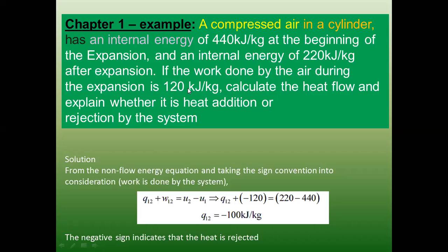Work, because here, the work done by the air means this work is done by the compressed air. So compressed air does work, which means the energy level of the air is reduced. It does work on the surroundings, not received but delivered work. So as a receiving of work, this is minus. So heat in plus work is minus, equals U2 minus U1. So this is the heat in, meaning this is a heat release.